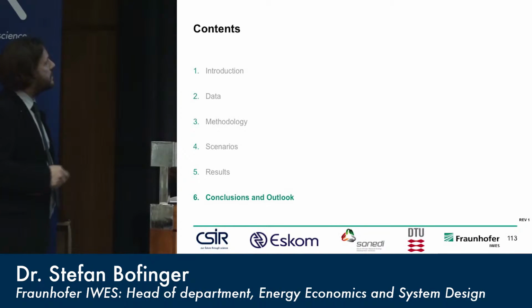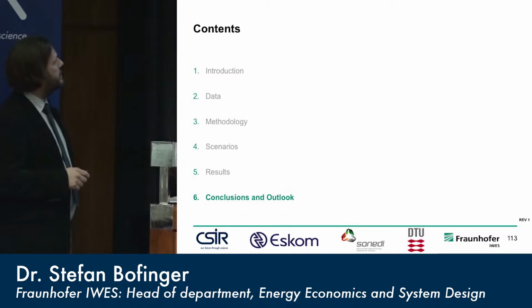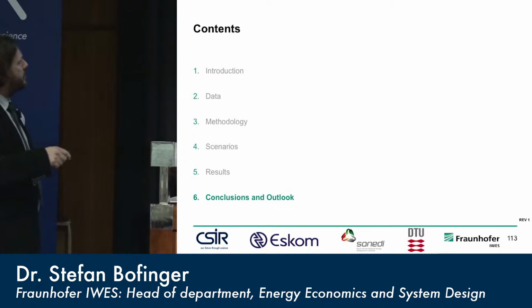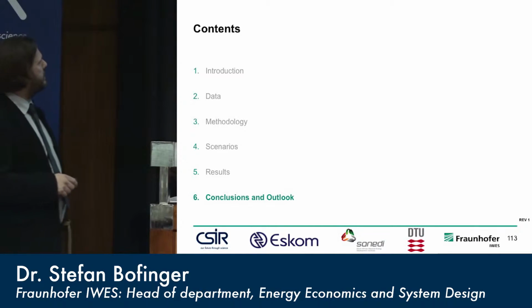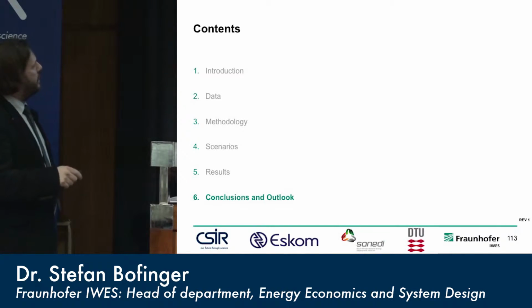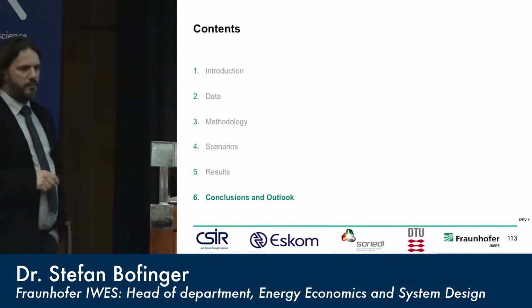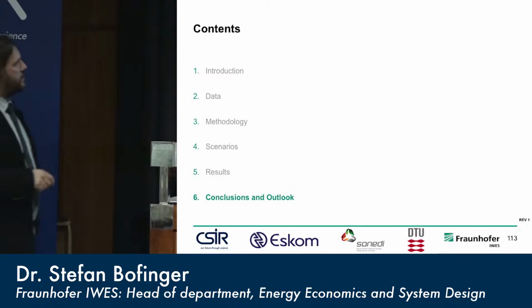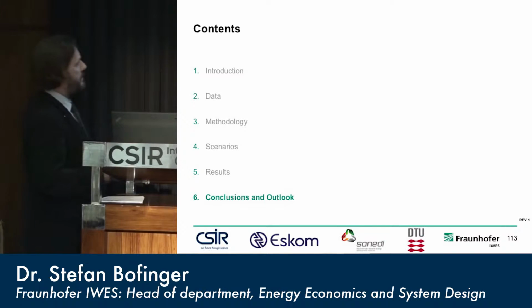This table summarizes it all. Here you see the different curtailment levels, 0, 5, and 10% curtailment per year, for only feed-in, and down there the feed-in and load, so the residual load. You see that if you do not allow any curtailment, you can overload the substation by 20%, or by 60% if you also consider the load.